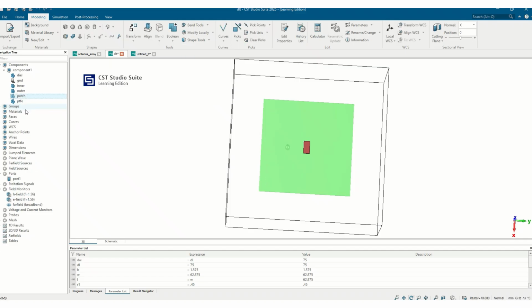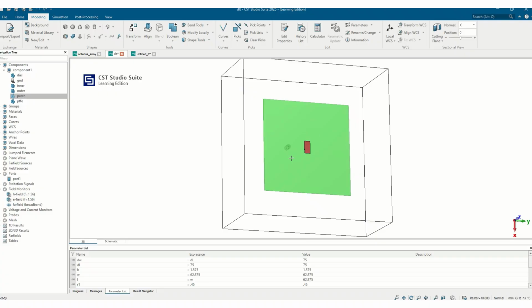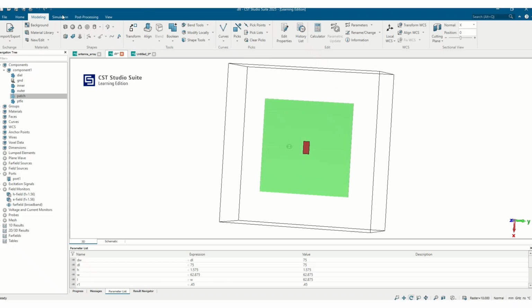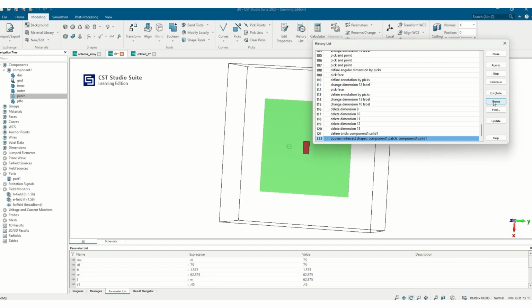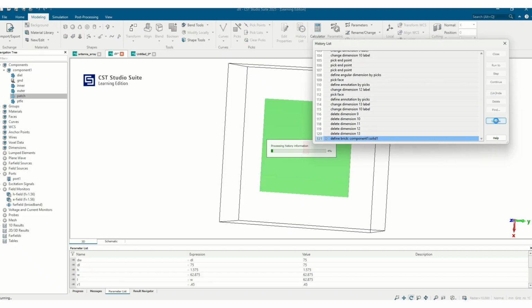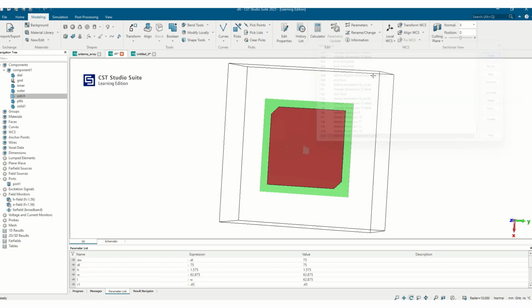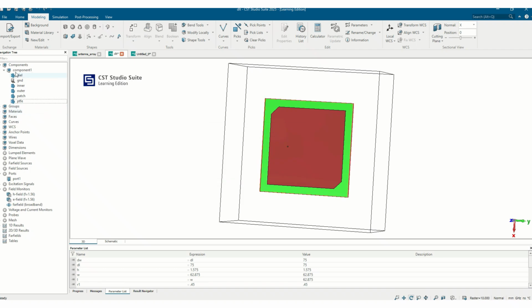So I just selected both. Here you can see that the intersection of both the patch and the structure is remaining here. That is how the intersect works. So these are some of the operations that can be used to create different types of structures. And this transform operation is for if you want to do some modifications like translation, rotation, scaling, or mirror.